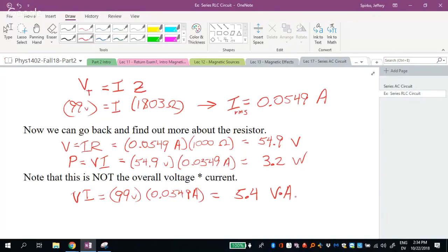And that's what they're really trying to get you to limit, the amount of current you're using from that device. So to run an entire computer system for 5 minutes, which should be enough to save your files and shut down nicely, you probably want a battery backup that has like an 800 volt-ampere rating and 5 minutes of runtime.